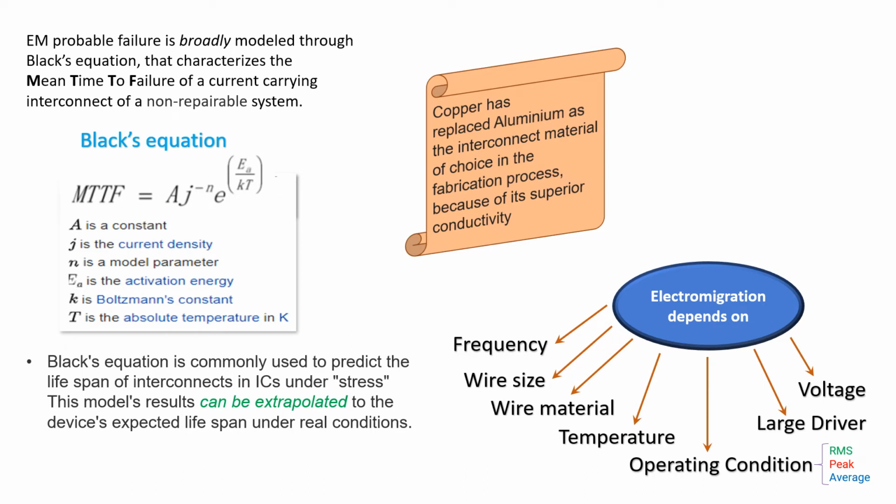If you observe the wire material, it would be better if it were gold or silver, but because of cost reasons, copper or aluminum is used. However, gold is also used in specific last mile connections. If you see, copper is way better, close to 5 times better than aluminum in terms of electromigration for the same reliability need.